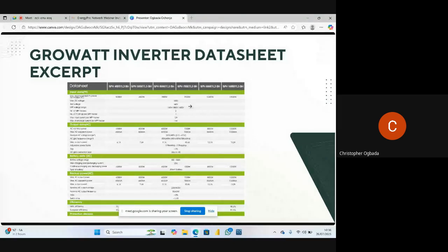This is something people neglect, but let me tell you, 90% of, and that's why you see some OEMs, they don't want to even honor warranty terms, because they've seen things. A lot of the issues that arise from inverter failing is as a result of this, right? So you must make sure that each of the cumulative parameters of your array match perfectly with this.